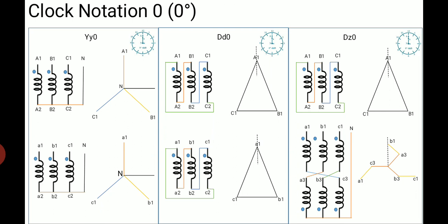Okay. The benefit of this is, if we make such a connection, it will help us eliminate the DC magnetizing component produced due to improper firing angles through power electronic switches like SCRs. If we make the reversal connections, the DC magnetizing component can be cancelled in each limb of the zigzag transformer. Another advantage is that the harmonic voltage present in the system can, to some extent, be cancelled by such winding due to its opposite connections.